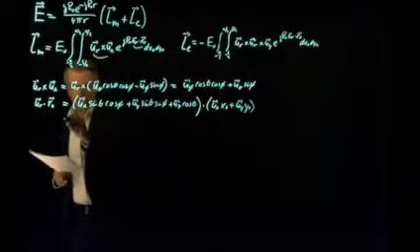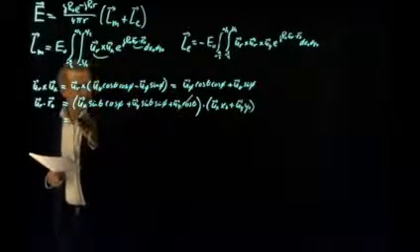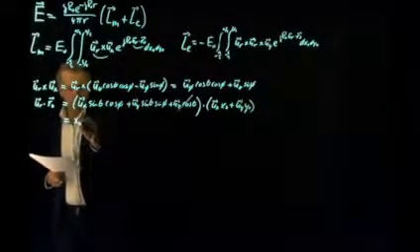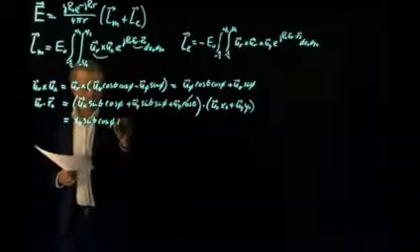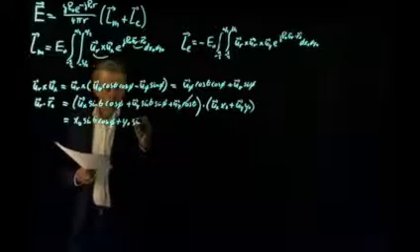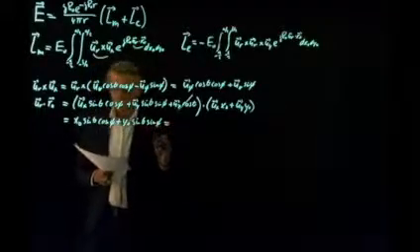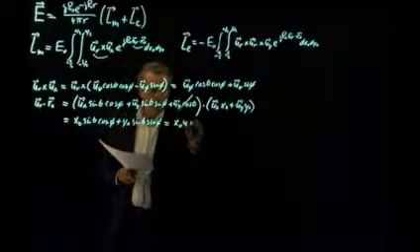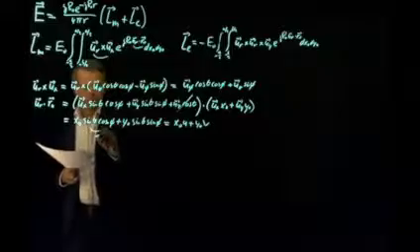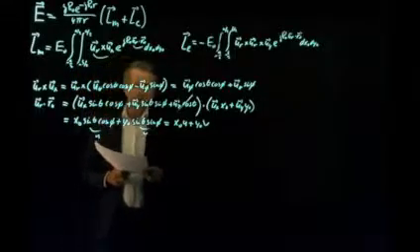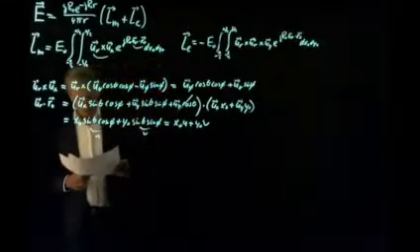Yeah, so that's fairly easy to work out. So this disappears, and we get x0 sine theta cosine phi plus y0 sine theta sine phi, and that can be written in a more compact form, x0 u plus y0 v. And u and v are given here, and u and v are commonly used in antenna theory, and we will more often use them.